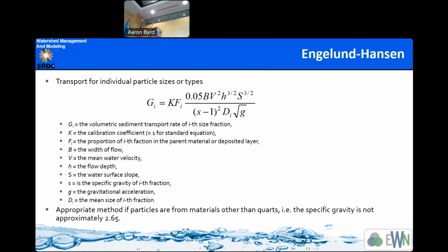Like I said earlier, this is a completely physics-based equation, the Engelund-Hansen, and it all depends upon the flow characteristics and the flow properties. Actually, you don't have to input anything in this equation. Although, because of our experience, we provide a calibration coefficient, which in the initial original form probably isn't there. Sometimes in some erosion processes, we saw that if we put in some calibration parameter, it gives a better answer, because there is nothing else to tweak around in this equation.